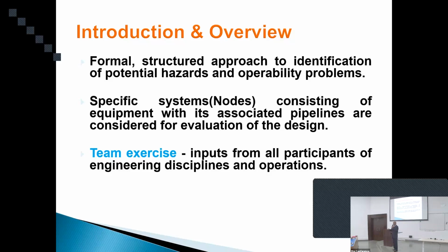They will say, no, this has not happened, or this is going to happen, take care. These types of discussions will take place in the HAZOP session. And there will be a chairman who will listen to all of this and evaluate whether what anybody suggests can happen is credible. Is it likely to happen? If it is likely to happen, yes, safeguards are to be seen. If it is not likely to happen, let us not do it.